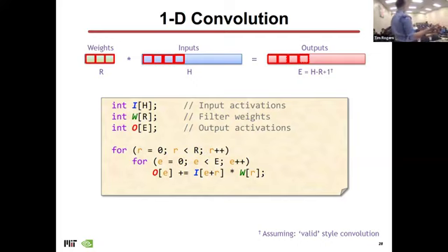Does that make sense? Yeah, so in that case, in the code, what would it look like to say, I want to pass this value to the next PE? Would that be like a store to some special magic address? There's no stores, right? There's no decoder, there's no front end running a real ISA. All that stuff has flowed, right? So it would really just be like when you output, you need to have some control, right? Because you need to know whether you're going to accumulate or send your output.